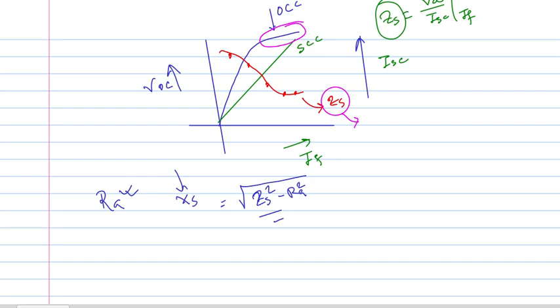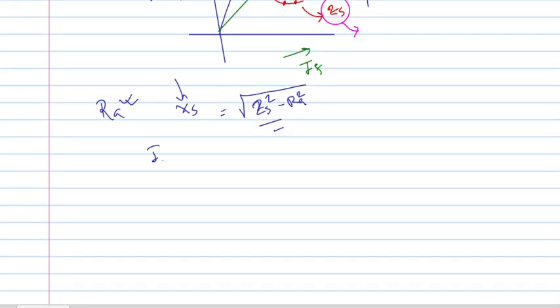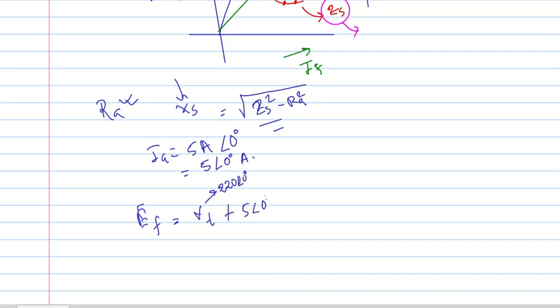Now under certain load conditions, say your Ia is equal to 5 ampere and the power factor of that load is purely resistive, so the angle is 0, so 5 angle 0 ampere current. What is the generated EMF? Say the terminal voltage per phase is 220 volt angle 0 plus 5 angle 0 times your Ra plus j Xs, that will give you the EMF, and this EMF in polar coordinates has two parts, the magnitude part and the angle part.